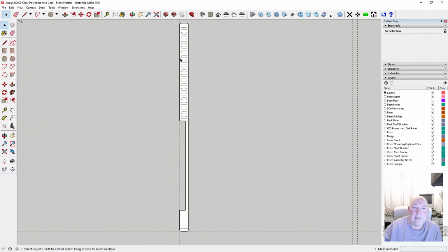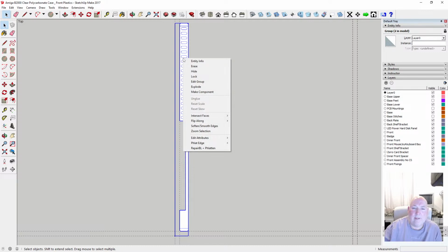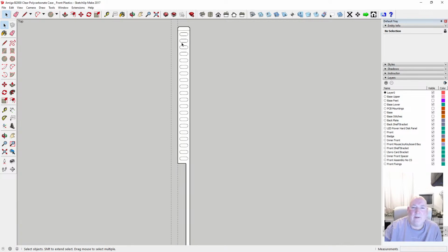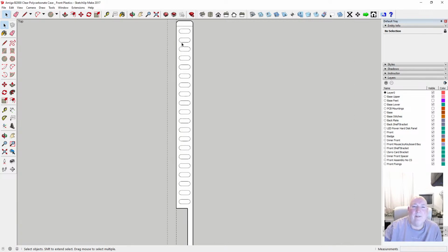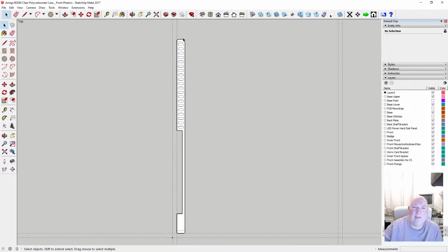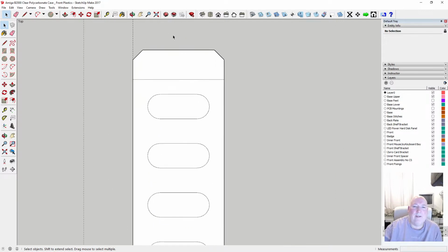Right, do we need to make that unique? Don't think we do, because it's not a component. That's fine. There's a reason for not making it into a component, really. You don't have to worry about... Okay, so this one is the pocket. So in order to get the pocket to be created, we'll mill it out round it, so this pocket can just be bigger and it'll avoid any corners and things.